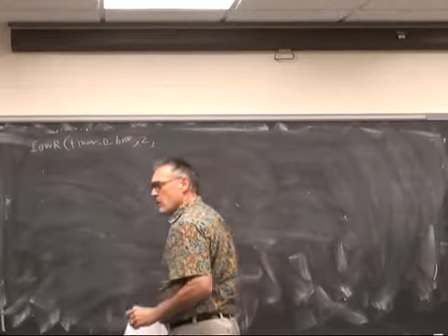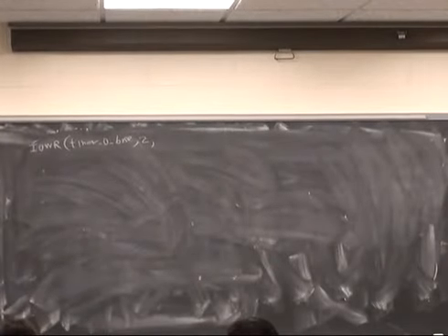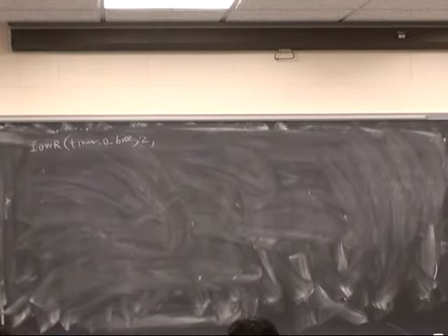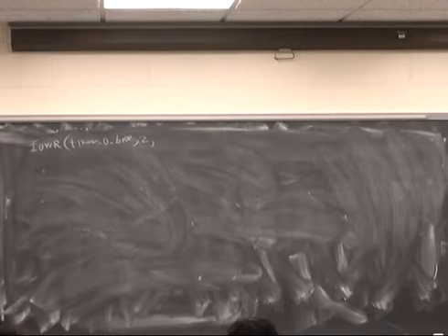And oh, why do we have low and high? Wait a minute. It's a 32-bit timer. This is a 32-bit bus. Why do we have to have a low and a high word? Because the timer was originally defined for a 16-bit version of the microcontroller, and they didn't modify it. And so you have to load the low 16 bits separately from the high 16 bits.